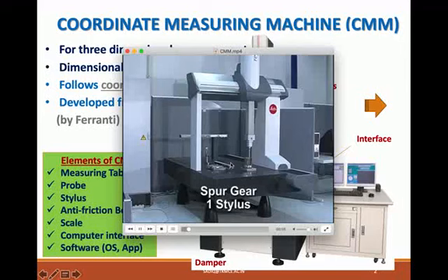This is a coordinate measuring machine. You can see that this is moving, this is moving. This is a bridge kind of CMM. This is one of the commonly seen configurations. So this is a table, this is a bridge, and this is one of the axes. You can see the probe. This is a workpiece, and you can see a white ball here, that is a qualifying sphere, and the granite slab will have an arrangement to fix the workpieces, and these are all mounted on dampers.